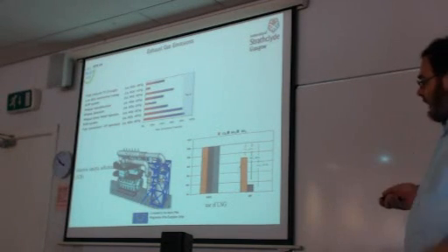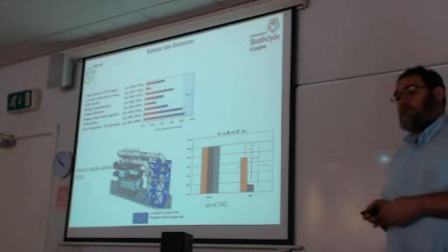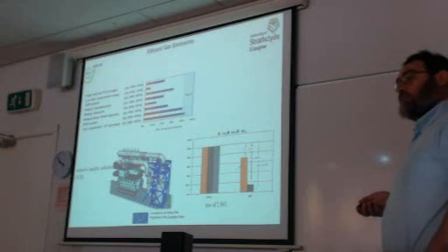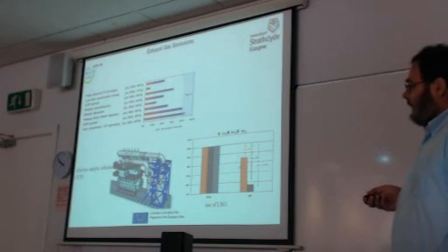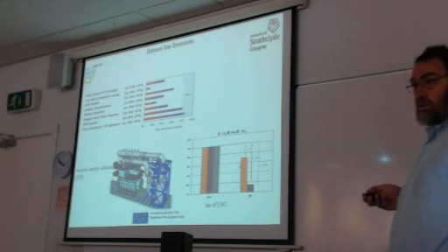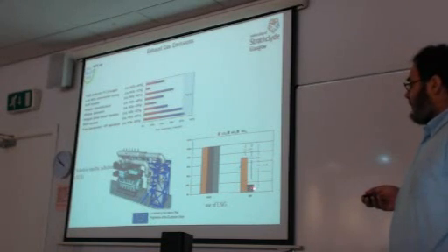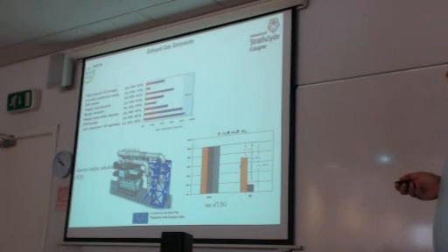And then the use of LNG, which actually is the use of natural gas. LNG is a form of storing the natural gas on board ships. It can provide a reduction of CO2 by 30% and an increase of efficiency, because the efficiency of the engine and brake power with fuel consumption is proportional to CO2 emissions. As I mentioned, there is a reduction of NOx by 85%. And as far as LNG, which means liquefied natural gas, does not contain sulfur or contains only a tiny amount of sulfur, then it means that SOx can be eliminated.